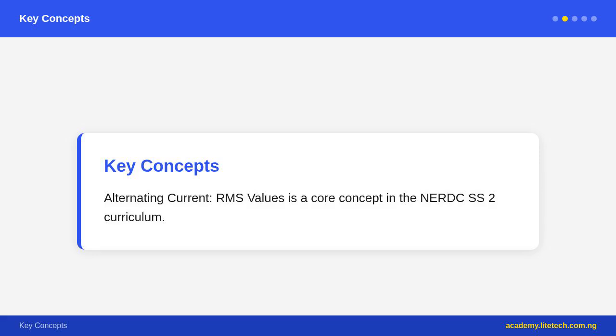Average power over a full cycle, P_av equals I0 squared R times the average of sin squared omega t. The average value of sin squared omega t over a full cycle equals 1/2, which can be shown using integration or the identity sin squared x equals (1 minus cosine 2x)/2. So, P_av equals I0 squared/2 times R equals (I0 over square root 2) squared times R. The RMS current, I_RMS equals I0 over square root 2 equals I0 divided by 1.414, which is almost 0.707 times I0.